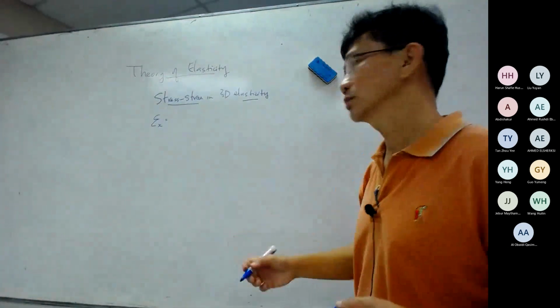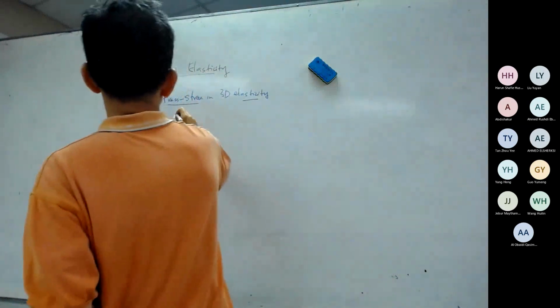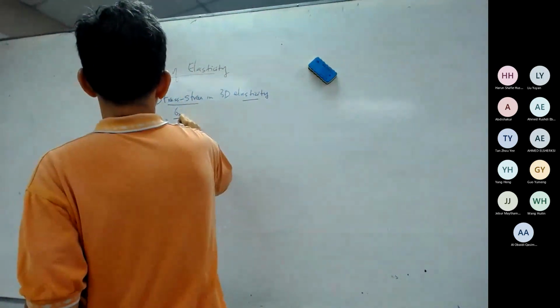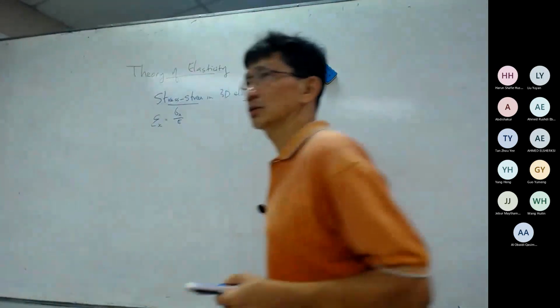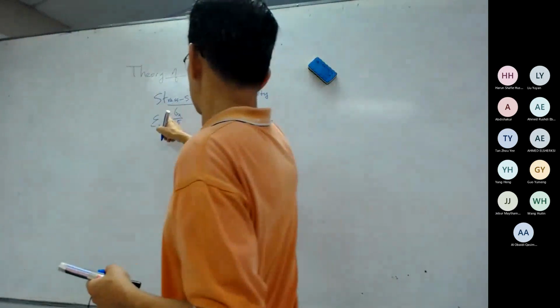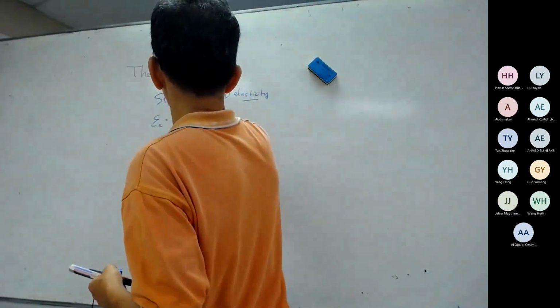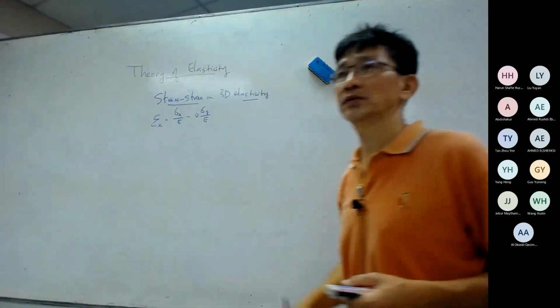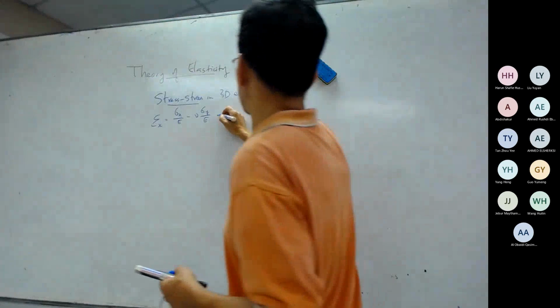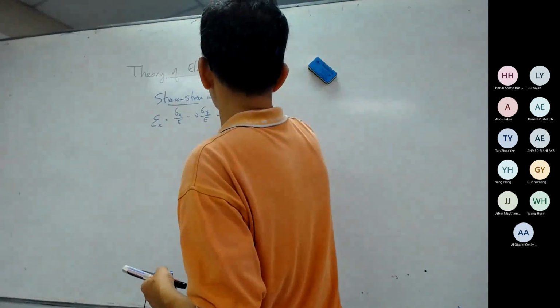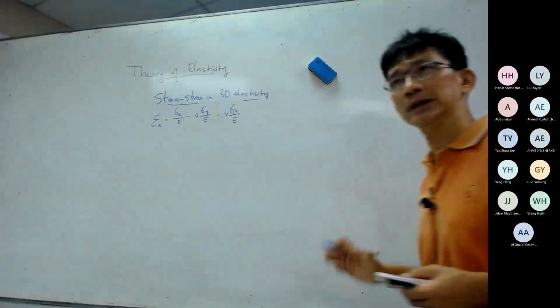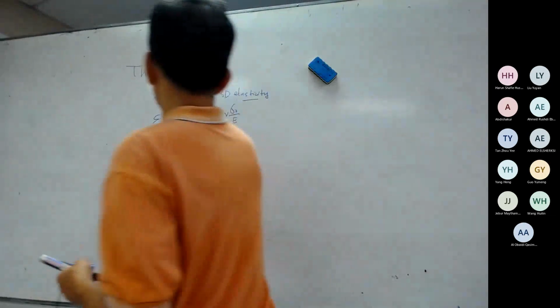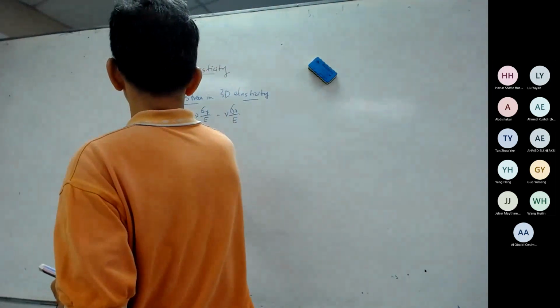And I think many of you remember well, it is always first related to sigma x, no Poisson ratio. Then only we have the Poisson ratio effect. The stress in y direction will cause negative strain in x direction. And the positive stress in z direction will cause negative strain in x direction. And let me finish this. This is the basic one.